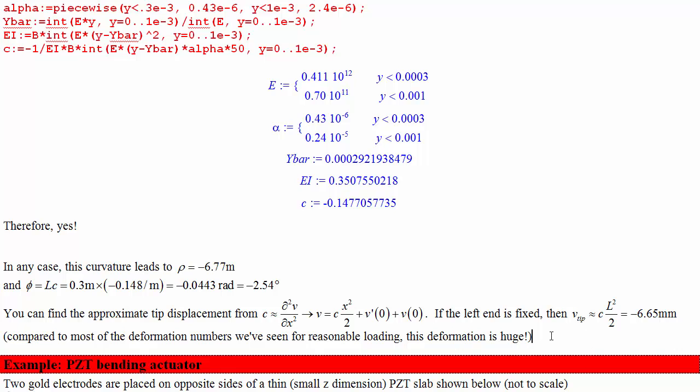Basically, you would twist the dial to set the point where you want the thermostat to turn on. That kind of coils and uncoils a spring, and then as the temperature changes, it deflects this coil because the coil is made of two different metals in a strip. So that moves one end of it, and when it moves because of the temperature change, then it creates a circuit. It makes electrical contact to some other plate of metal, and that will turn on or off your heater depending on whether the temperature is too low or too high.